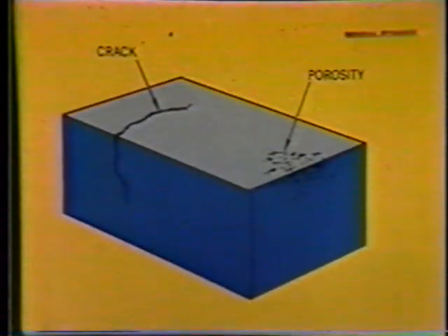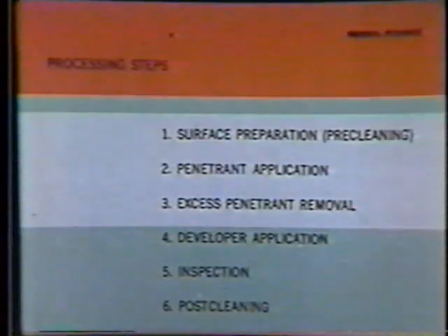Emulsification time used depends on the specimen's surface condition and the type discontinuities sought. Average times range from 1 to 3 minutes, seldom exceed 5 minutes. Correct time is determined by experiment. The pre-cleaning, penetrant application, and removal steps are repeated using different emulsification times until desired wash is obtained.